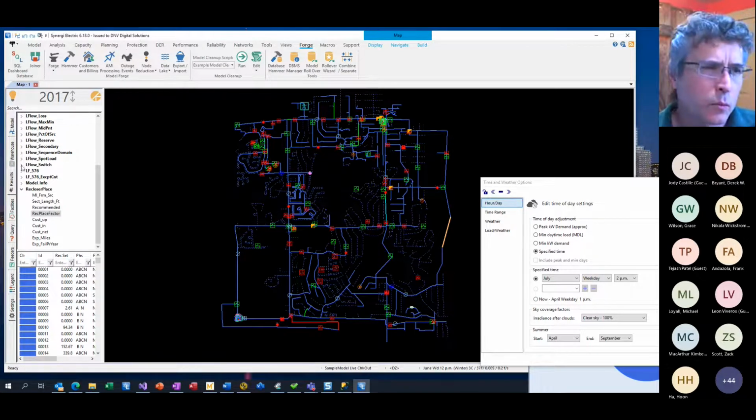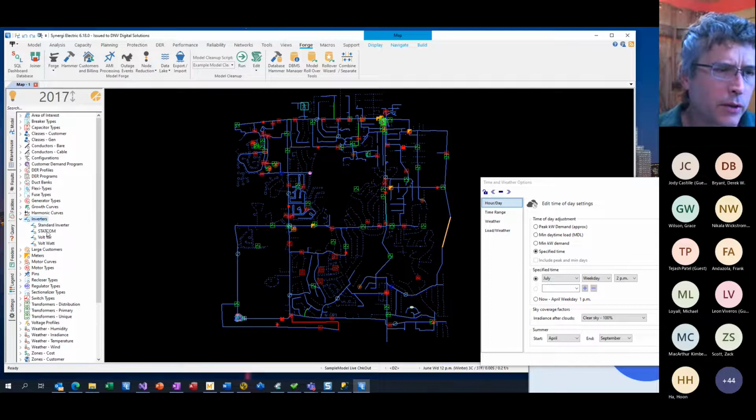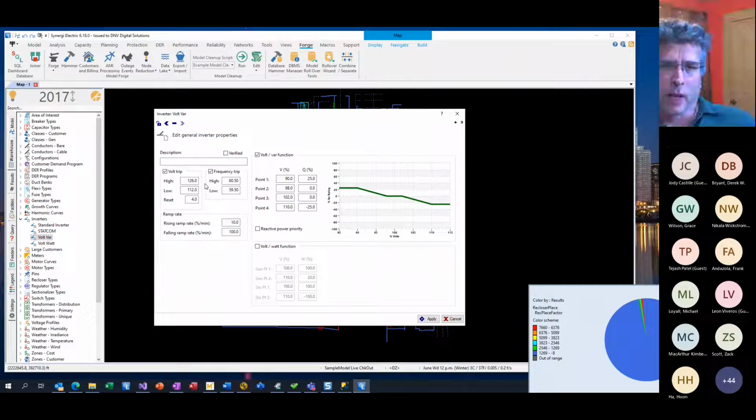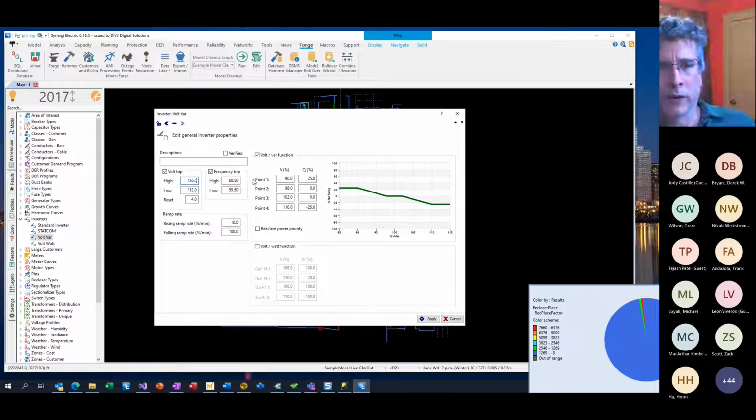We did some work on inverters over here. I'm not spending too much time here on inverters. We had a cycling problem where an inverter would trip due to high voltage. For example, this thing would trip and the generator was miles away from the feeder. So there was a significant impedance between the generator and the source. When the generator tripped, the voltage would drop below the trip point and then it would activate again. And so it would just sit there and cycle off and on because of that.